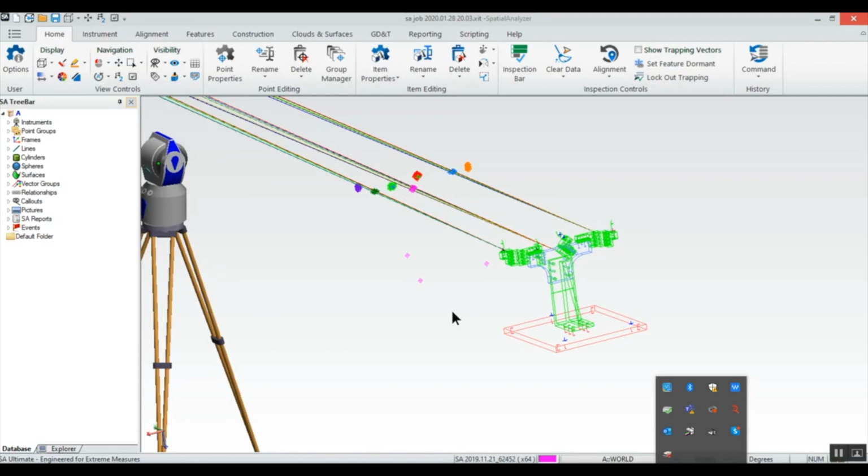So we've got, I'm going to go ahead and turn on point label so we know what's what. So we want point 1 to be zeroed out. Point 2 in essence is going to be zeroed out as well because we're going to scale between point 1 and point 2. So this should be perfect to nominal. This point should be perfect to nominal. This point should be perfect for Z because we're going to clock in this particular example in the Z direction, but we're not really so concerned what X or Y is. It's going to be what it is.